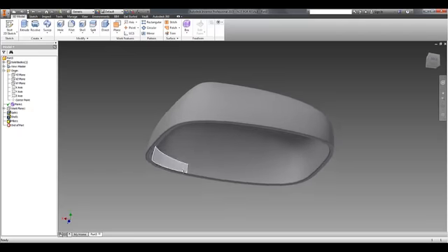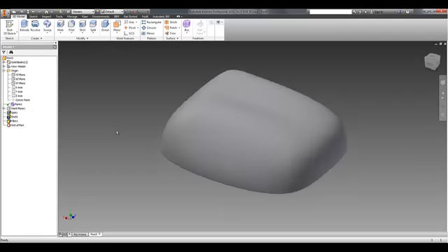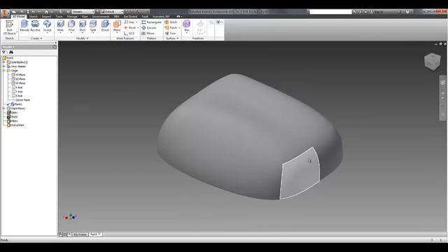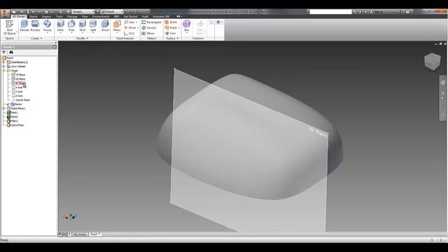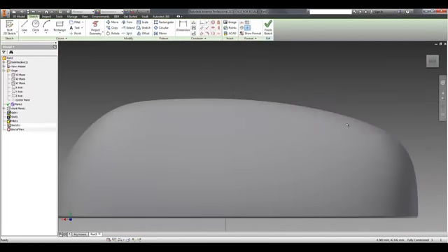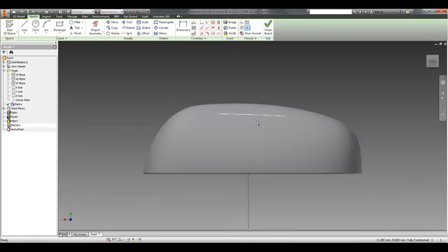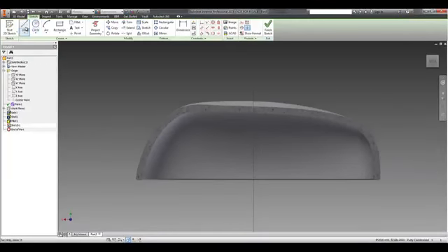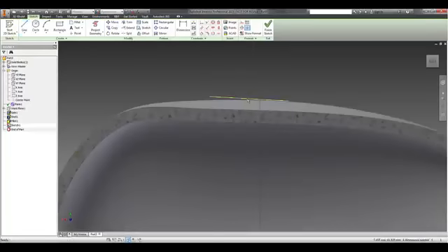The other really handy tool in the freeform editing is the ability to match that T-spline surface to some sketch geometry. So if I go and create a sketch on the center plane, and I decide maybe I have some reference geometry of the underlying part, I could derive in a sketch from another part, whatever it might be, I might know, just hypothetically, that I need an edge along the top. That's the finished result, or my reference. That's where I want that T-spline's edge to actually lie.